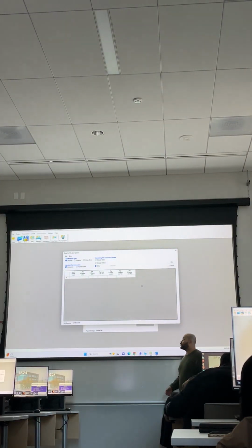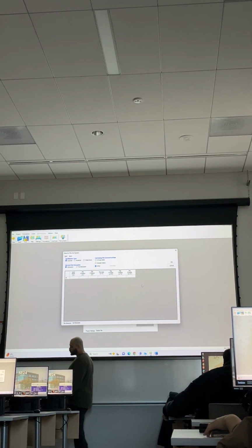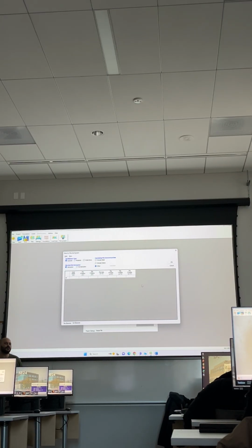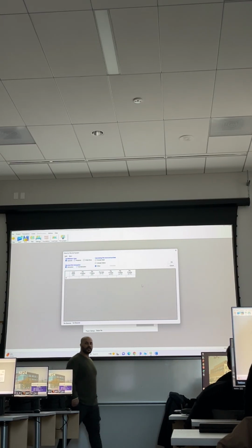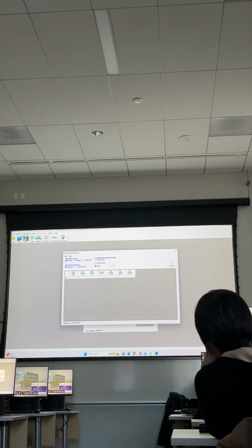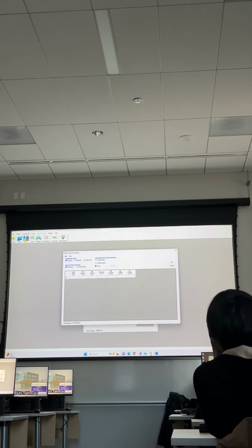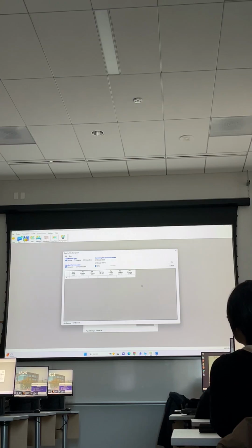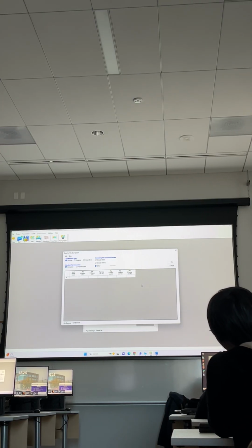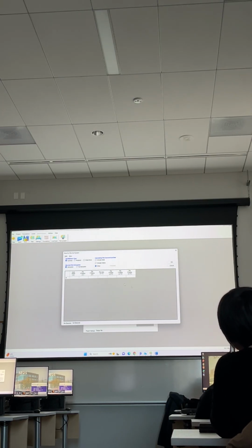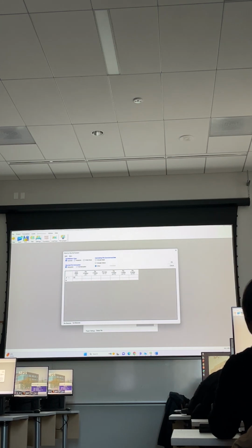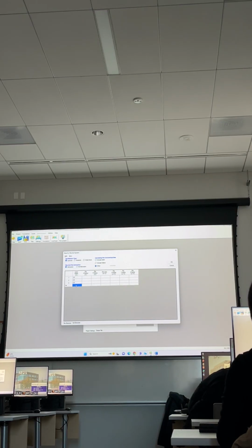But actually, we're gonna use this window to define if we have a layered soil. We assume that the pile is 10 meters, and that every 2.5 meters there is a different type of soil. So I will assume 4 layers here: 2.5, 2.5, 2.5, 2.5.